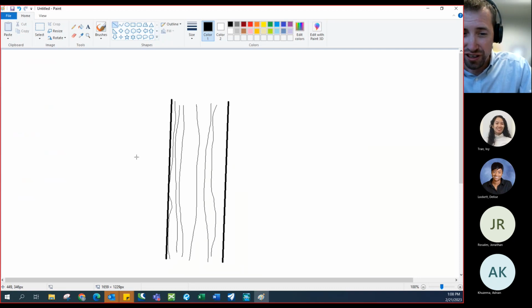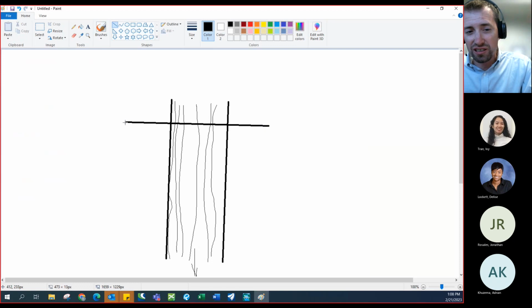So your cross sections for a perfectly straight channel are just going to be straight lines. And remember, if this is going downstream, always think like HEC-RAS. We're looking downstream, so we want to draw from left to right. Some software programs will take care of this for you once they know the direction of flow, but just in case it doesn't, I would always draw them starting from the left side of your cross section to your right side. In the case of a regular channel like that, it's just going to be straight lines.